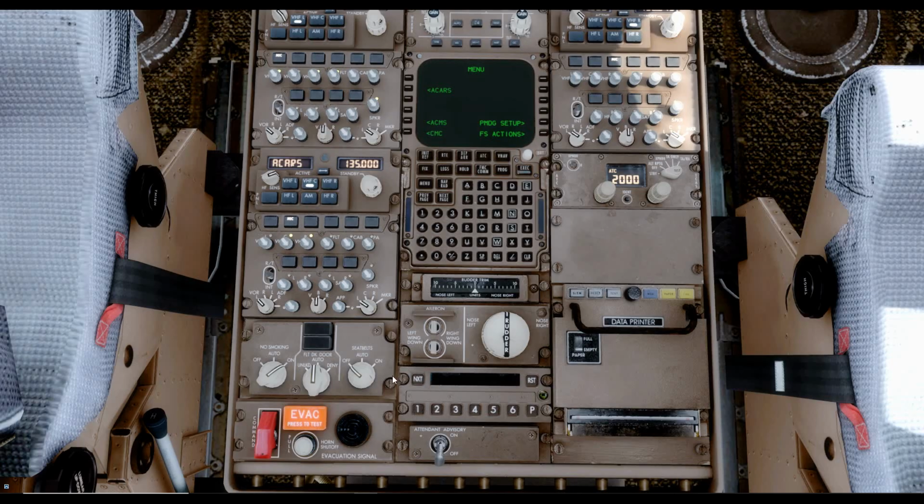Moving down to the passenger signs, the no smoking signs are always left on, and the seatbelt signs should be on as well, but we leave them off while we're refueling, and we only turn them on when the refueling has completed. So once we've been told that the fueling is finished, usually when the fueler would come up to the aircraft and or get on the interphone and tell us that the fueling is completed, then we can switch the seatbelt signs on. We'll leave them off for now.